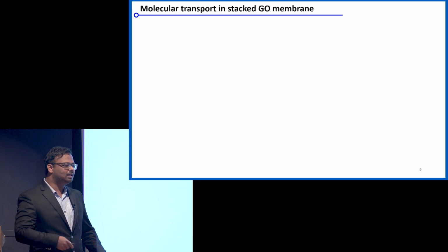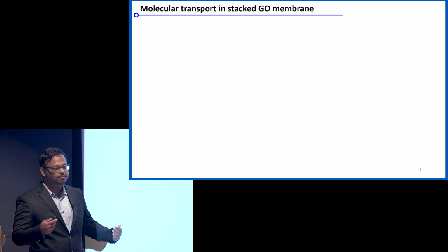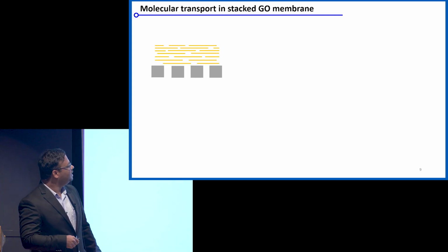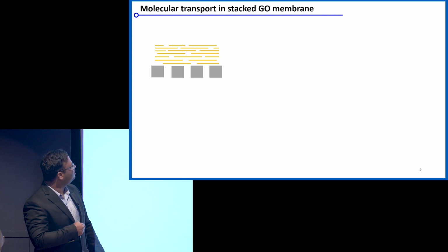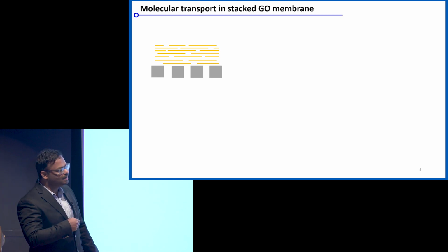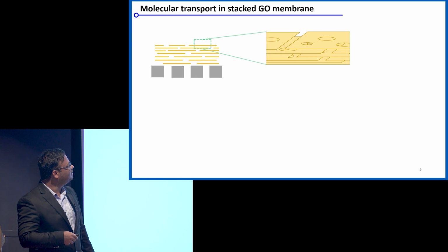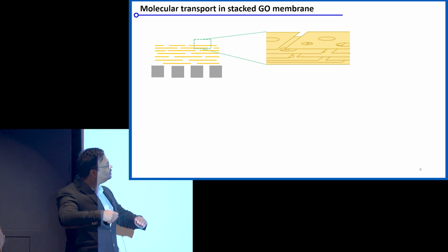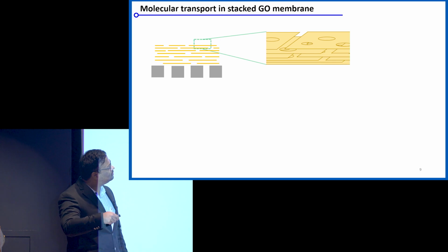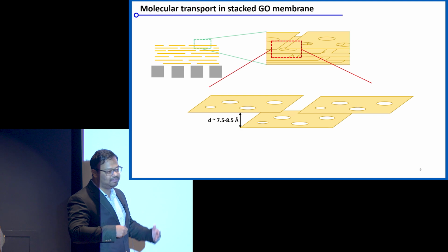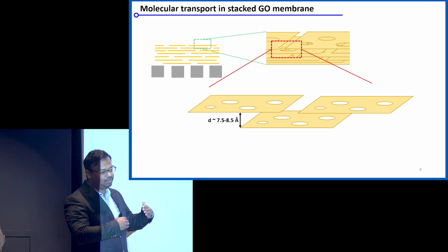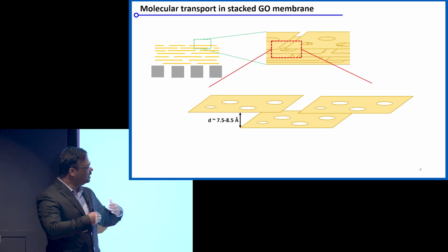Traditionally, over the last 1.5 decades, what people have been using for graphene oxide membranes is to take graphene oxide flakes, single flakes dispersed in water, and stack them up on a porous material, and this stacked lamellate is the separating material. If you look at the top of this graphene oxide, you can see the flakes, and with further magnification you can see the flakes have a spacing between them of around 5 to 8.5 angstrom, depending on the synthesis process.